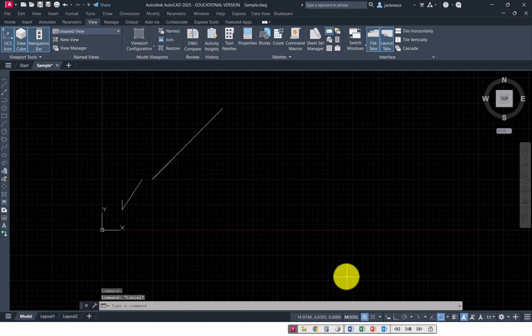Now we have one other thing here called polar coordinates, and I'm going to turn dynamic input back on. Polar coordinates is when you have to draw a line at an angle. You're going to find as you're working through AutoCAD that it's much more accurate if you type in your distances and even your angles. We have other ways of dealing with angles sometimes, but it's more accurate if you type it in on the keyboard as opposed to drawing it with a mouse. I'm going to get into some examples of that in another video.